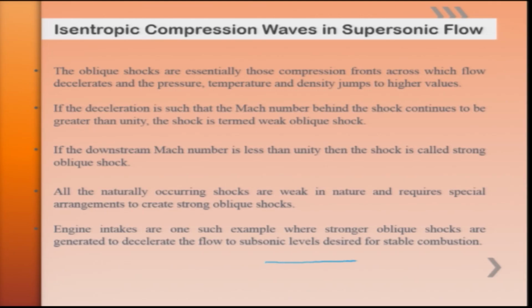We know that ramjet and scramjet engines do not have any turbomachinery involved, and they have a very simple geometry. A ramjet engine has an intake, after that a combustion chamber, and further a nozzle to exhaust the gases so that it can gain thrust.